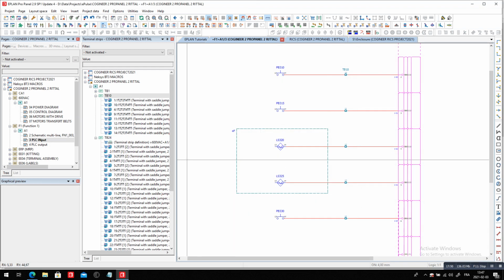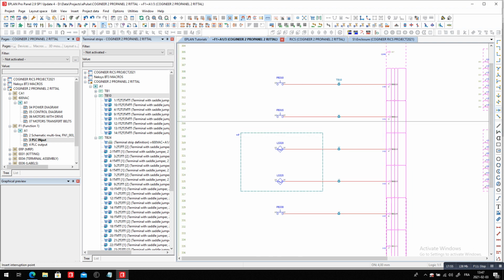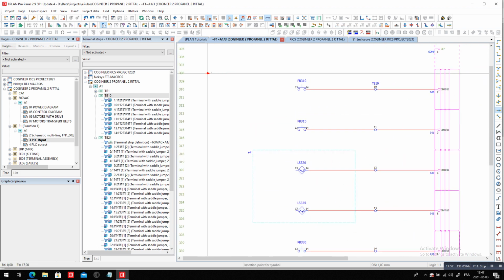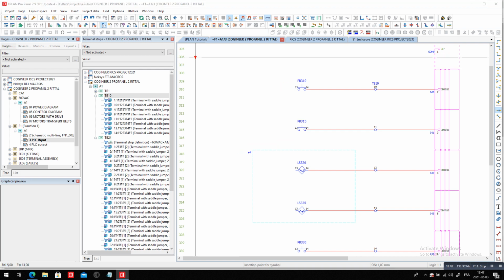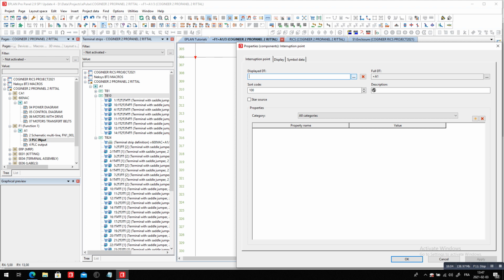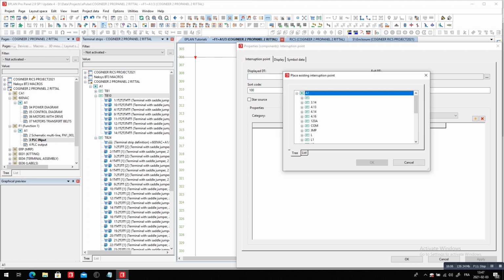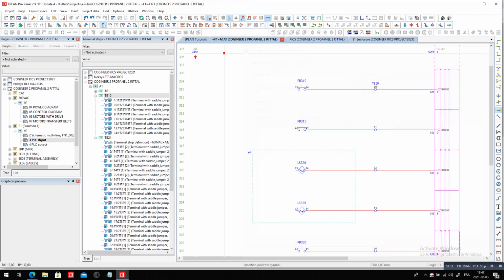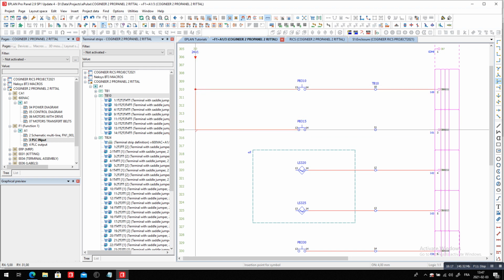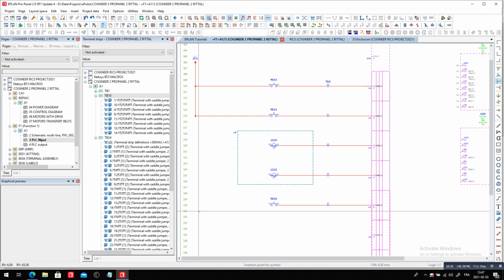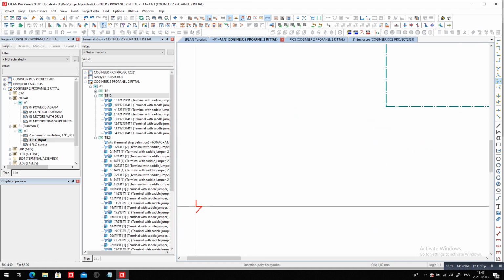Now let's concentrate on that 24 volt here. Now I may have created a 24V1 specifically for the door. So when you look here, I say, okay, I'm going to bring in the 24V1 onto all the elements that are on the door. So I basically have the door here, I have the door here, and of course, when you're looking at this T node, you are specifying that this is a daisy chain, okay?